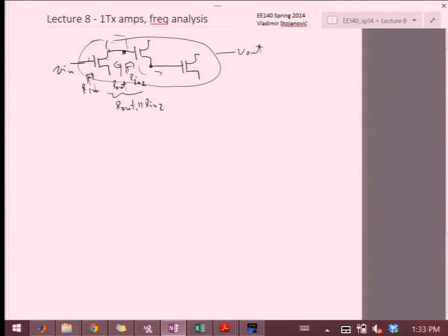The point is that in a BJT, I would be seeing whatever's downstream over here. So I would have to estimate what that emitter resistance is, and I know from what I've done previously with common collector stages that the emitter resistance gets multiplied up by 1 plus beta to be seen from the base, right? So I'm going to be using those kinds of formulas.